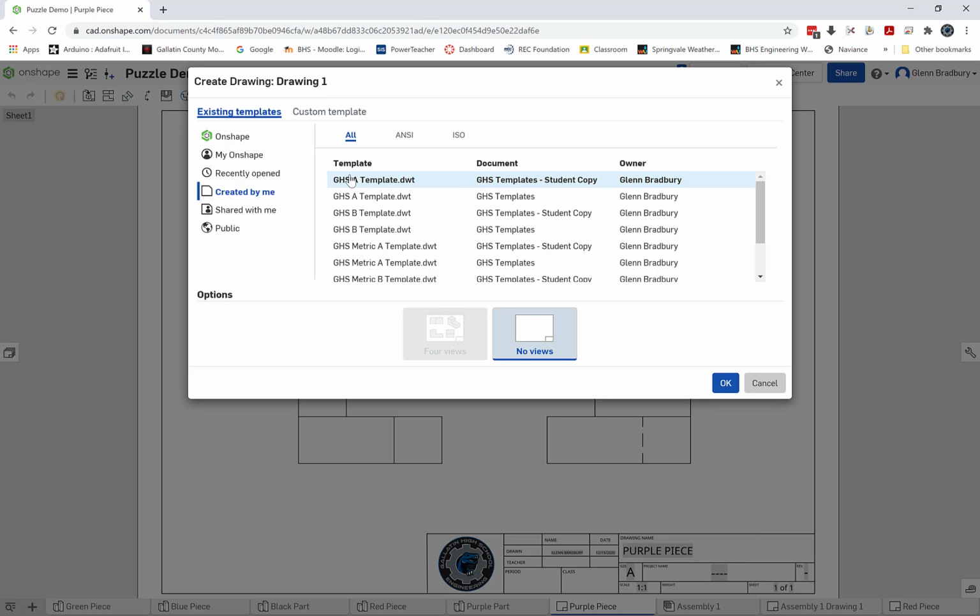These views are what you would see on the view cube. So if I switch really quickly to the red piece, you can see that my front view is referencing this view here. My top view would reference that, back, right side. Now it's kind of wonky because I'm orbiting. If I wanted to, I can just click on the right side. So you can see that the right side, when we go back to my drawing, is the same right side. It's just not shaded. So this is how a 3-view drawing will be laid out always.